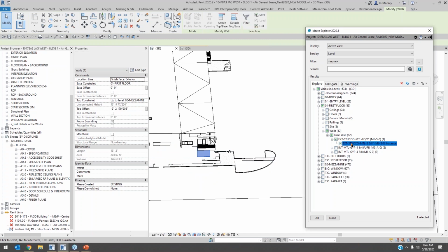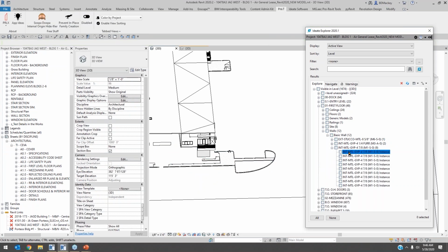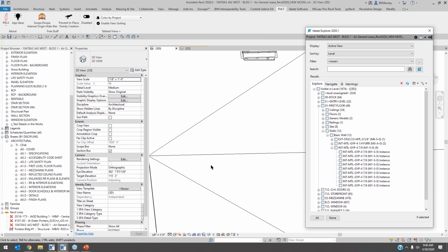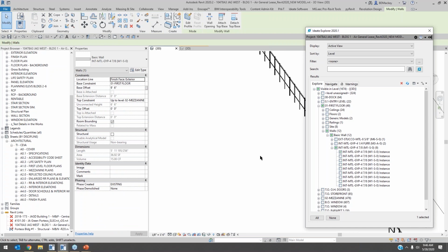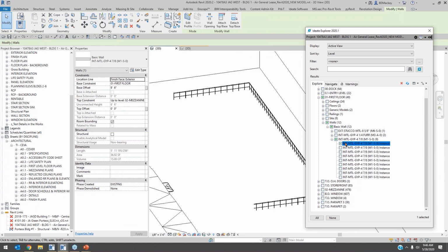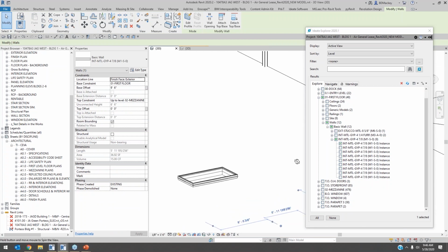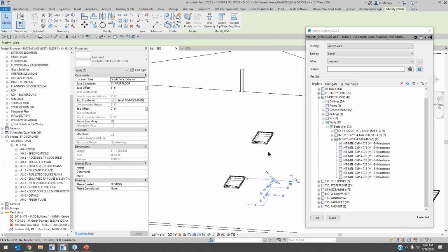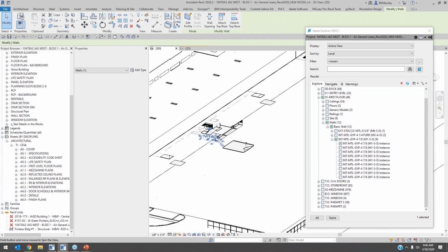So that is one thing that I do often, and it frustrates me: I'll double click it to zoom into the object. I'll do a different one here. And then I'm like, okay, let me start orbiting. If you double click it, you still need to click it to select it. So a double click is just to zoom into it. A double click is not a, hey, let me select it for you. I screw that one up quite often, but now you can see it's probably on a weird work set. Yeah, it's on an existing work set, or there's a roof in the way, but I can start seeing that